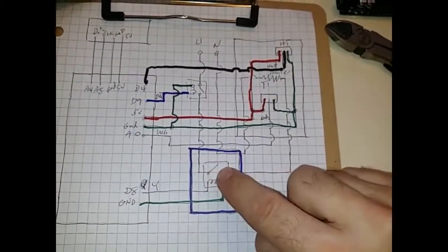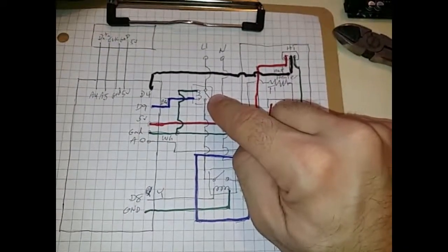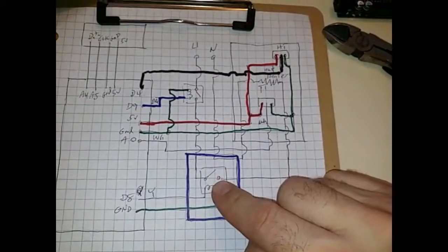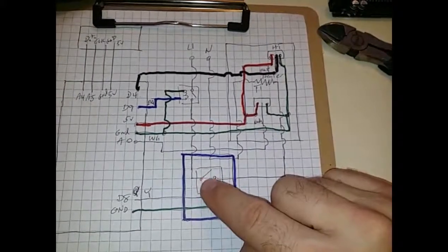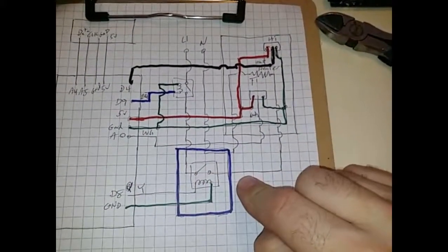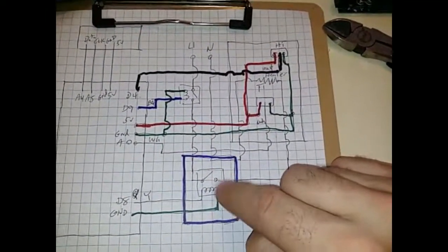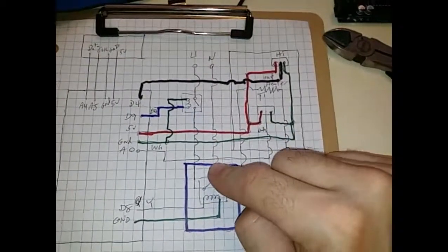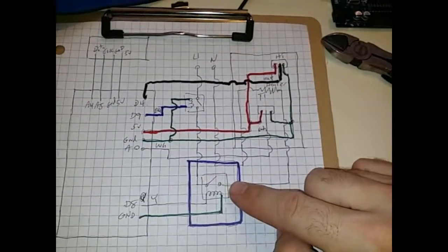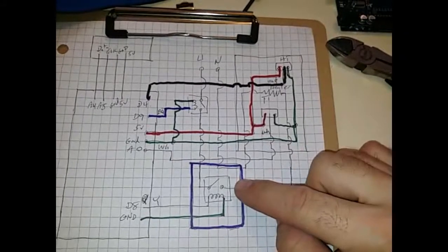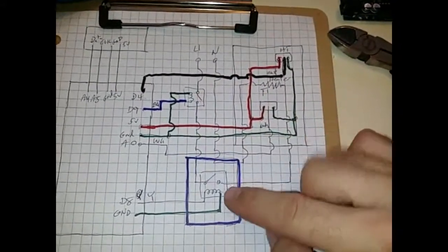Then there's a secondary relay for the switch that will toggle 3 times. So this engages when the heater turns on, and then after that it pauses, and then you'll hear 3 clicks. That's this relay, and it's switching the power switch from low to medium to high. The reason I don't have just one relay is for safety, just in case I have a defect in one of my relays. It won't just stay on while we're not at home and get an overheat and crack the mirror, or, well, I don't know if it would crack the mirror, but it's not ideal. So that's just for safety.